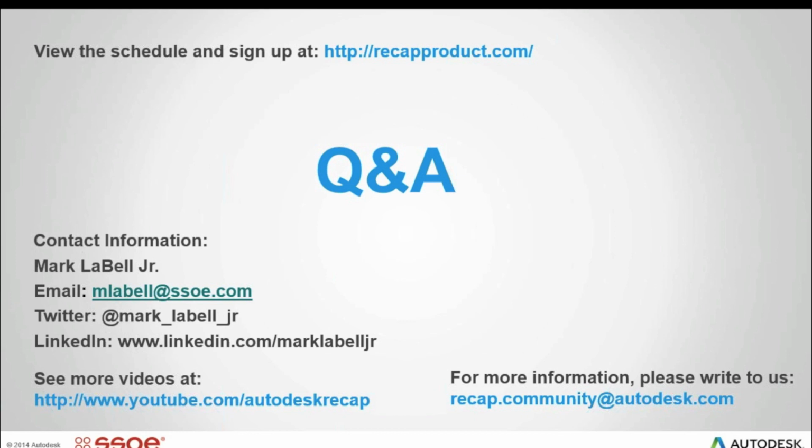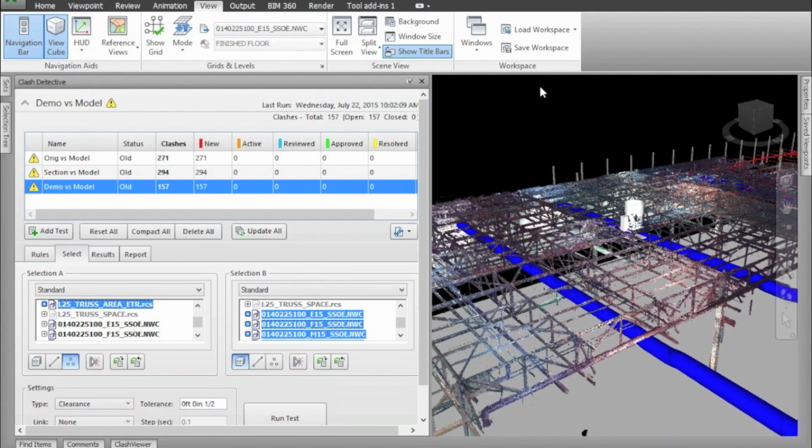All right. We have a couple of questions about the pipes and ductwork and all of that, asking whether that was just a lot of detailed selections in ReCap or whether you used a separate modeling package to create those selections. That was all done in ReCap, actually. And that's why I mentioned earlier why we've done so much more now in terms of reality capture. We can take on more work because of the tool set and the simplicity of it.